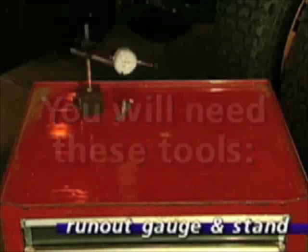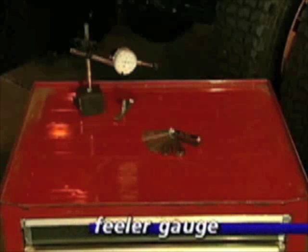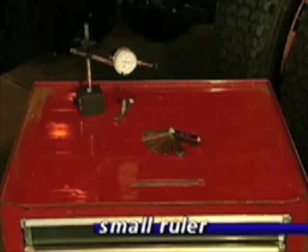The following tools are necessary to properly conduct a runout investigation. A runout gauge with stand. There are several on the market. Your Michelin representative can show you how to obtain an accurate measuring device at a reasonable cost. A shop feeler gauge, capable of readings as low as 5/1000ths of an inch. A small ruler to measure the guide rib motion.